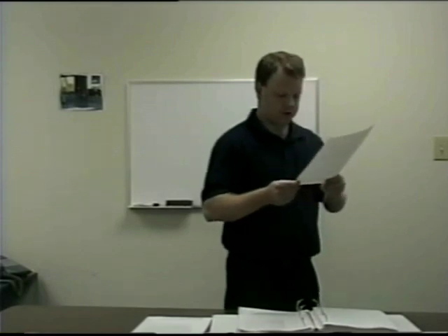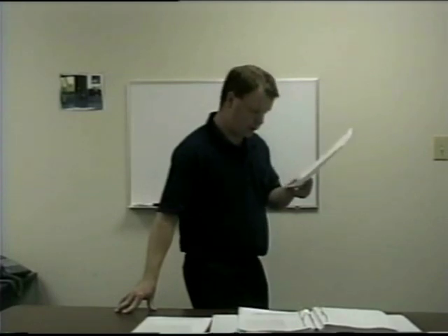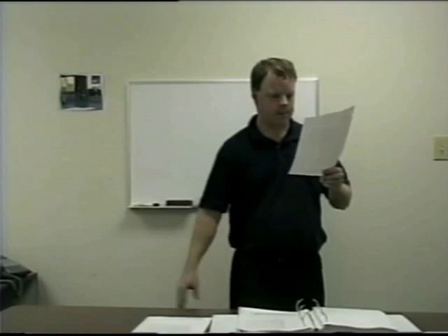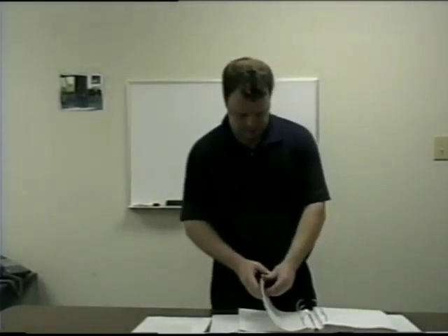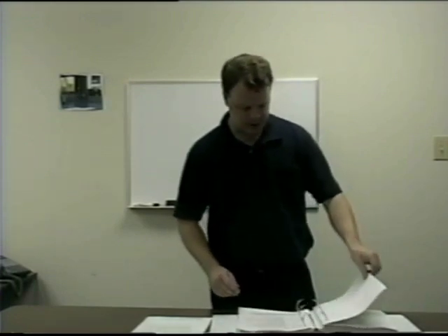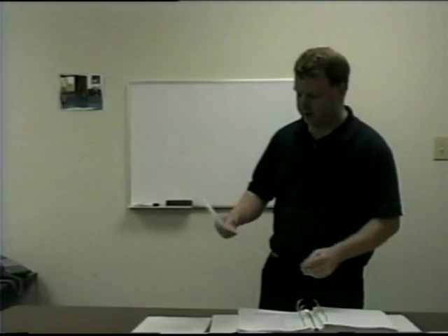Verify fire rated systems are installed in accordance with UL systems. Ensure hold down clips, if required, for acoustical matter is less than 1 pound per square foot. And verify hangers anchored to concrete support systems are installed as required and fastened by twisting around rebar. Very detailed inspections in here. Making sure that nothing slips. That architect comes on your job, he's not going to find anything that you're not already aware of.